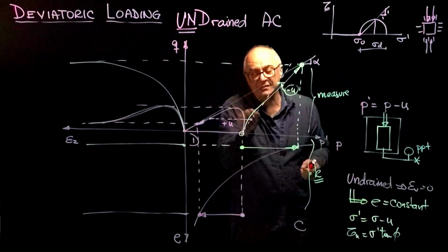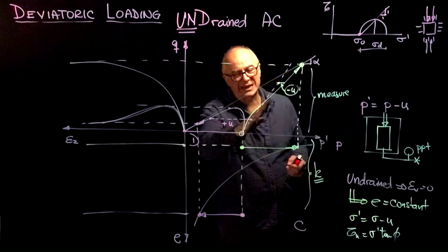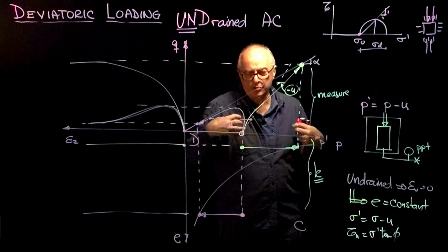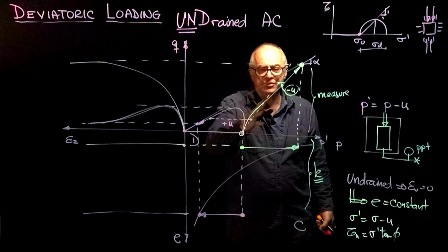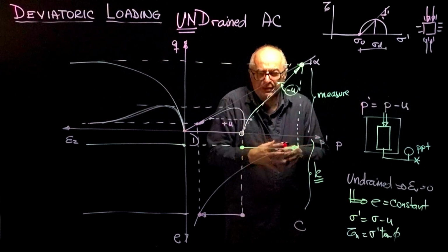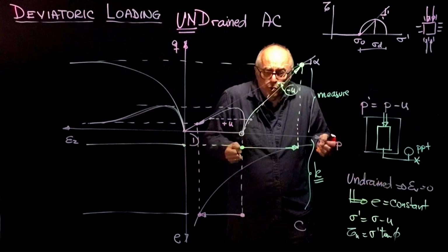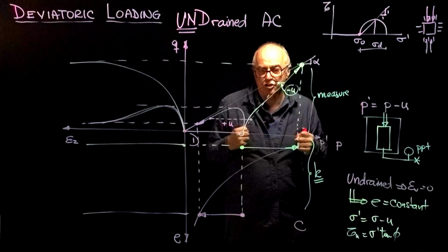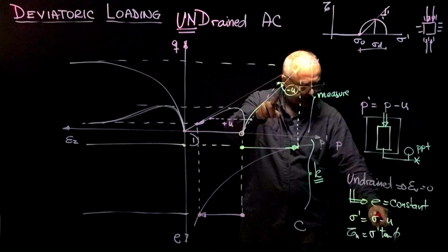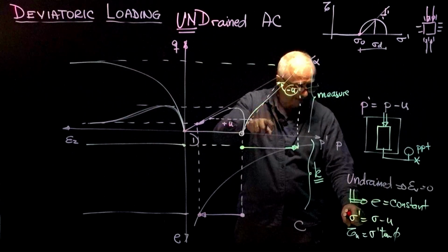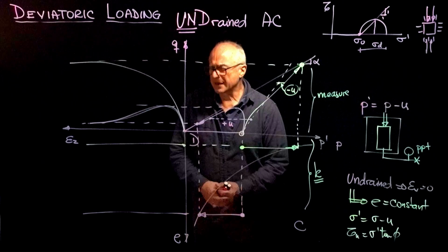In the case of the dilative soil, in total agreement with the drained case, at the beginning it tries to contract, but it really can't, so there will be positive pore pressure. It will be to the left of the total stress line of what we are externally imposing. But then, very soon, we'll recognize that in order to continue deforming, it has to dilate, but it can't. It wants to dilate, but it cannot pull water in, so the water goes into tension. And that tension adds to the effective stress: because the pore pressure decreases, the effective stress increases, and the strength increases.